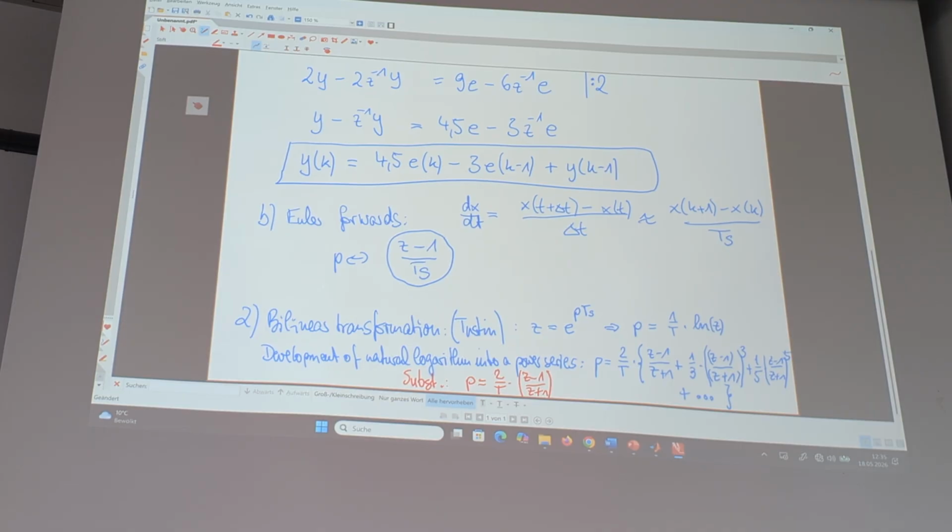And then for the PI controller, calculation would be quite similar. You just take the different substitution, put it into your controller equation, and then you get your d of z, and finally you can write down the software equation that you need to implement.